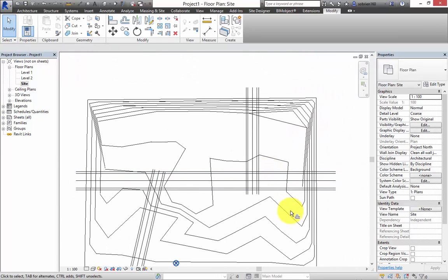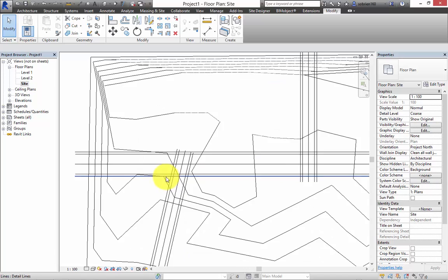And of course you can use the offset tool to make a cycle track, or maybe a grass verge, or whatever is required for the area that you're in. You can just use the offset tool. So now we've sketched out the position of the various roads that we have in there. The next thing we need to do is to deal with the turning circles, because you have requirements for the curve that you use to turn your car or to turn your ambulance or your garbage truck or whatever, they all have requirements for a turning circle, which also is in Neufert's or any architectural data book that you can find.